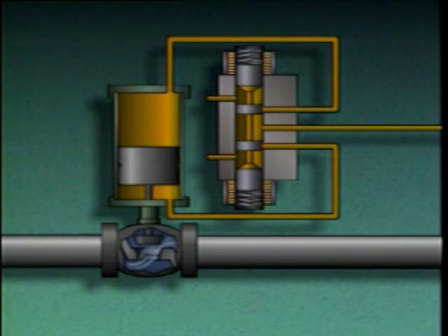In order for a double-acting hydraulic actuator to accurately position a valve, the amount of fluid entering the cylinder and bled from the cylinder has to be accurately controlled. The device selected to do this job is usually a pilot valve, or as it's sometimes referred to, a spool valve. To see how a pilot valve controls a double-acting hydraulic actuator, we'll use this simplified illustration.